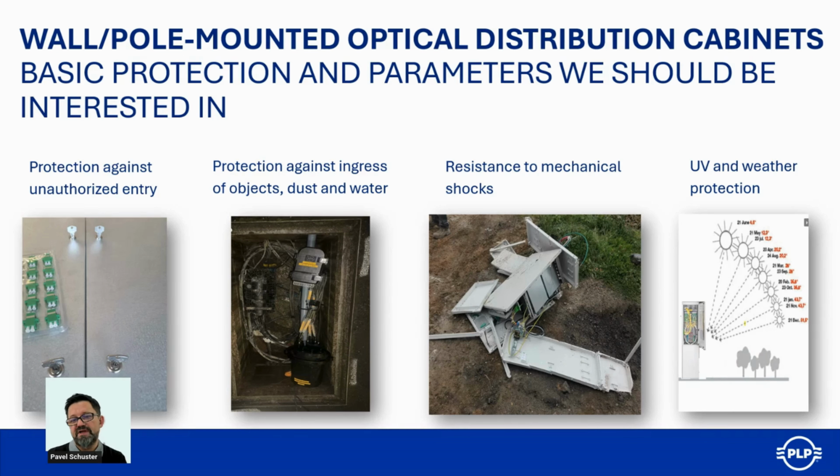What we do, in case you have a polyester cabinet, is it's very good to have some extra protection. In that case, I recommend using extra polish on the top or varnishing, where you put transparent varnish, and then usually the lifetime of the cabinet is prolonged by, let's say, 5 years, and then you don't see those pieces of glass coming out after a short time when it is installed in the field.